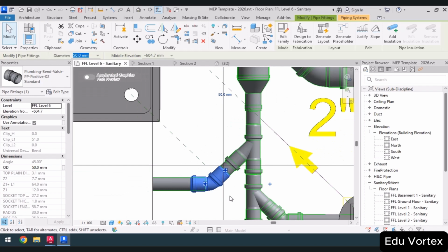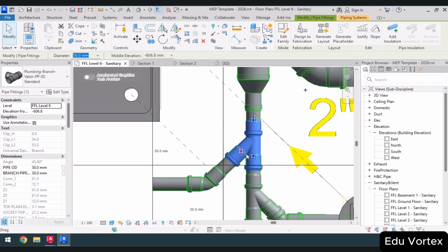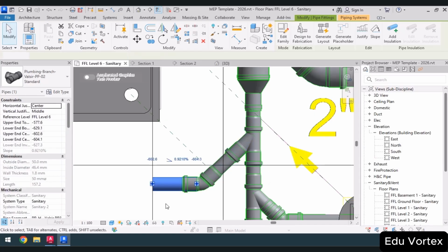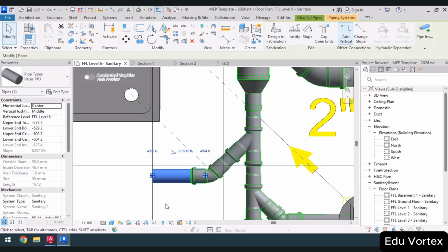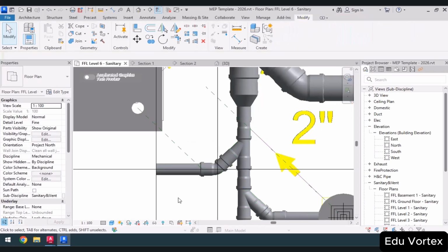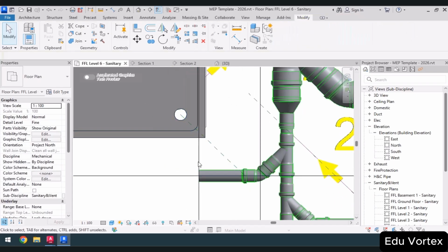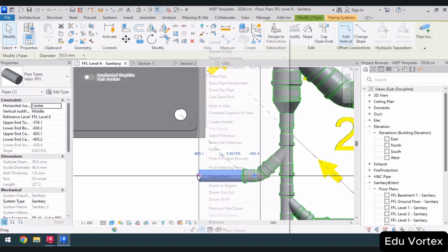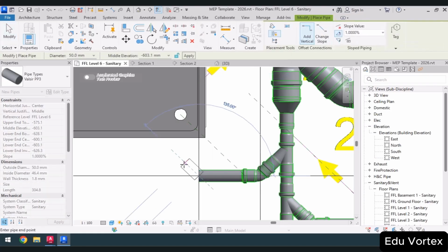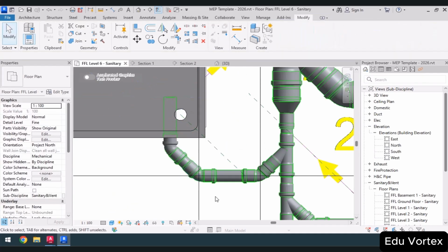I adjust its position slightly closer, moving both the T and this elbow backward within certain limits. So I cannot apply a 45-degree angle here directly. Instead, I right-click on the draw pipe at the 45-degree angle again, so it seems there's still some restrictions, so I'll put it slightly forward and draw it out.